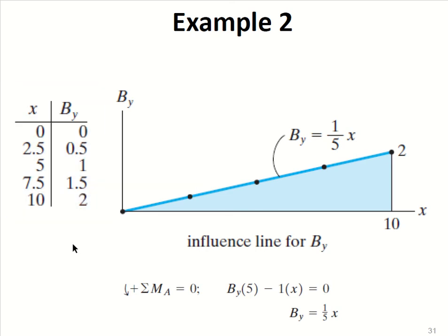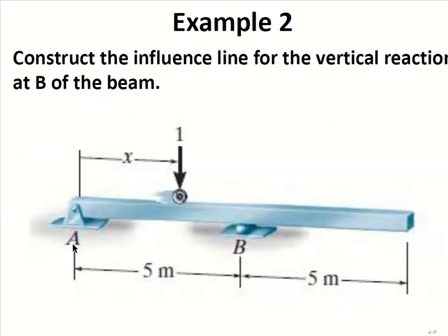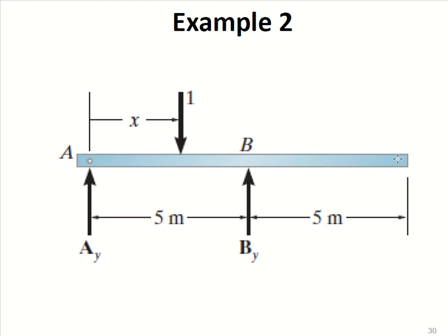Why? Because there is a bending moment included in it. See, when the load is at this point, the reaction at By is 2 times that of this load. Okay, because one kip is the reaction and one is the reaction due to the moment, because this one kip or one unit is producing a bending moment of 5, and these reactions have to produce a counterclockwise bending moment. So at A there will be a negative load and at B there will be a positive load. So 1 plus 1, 2.